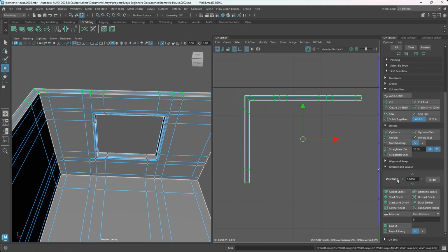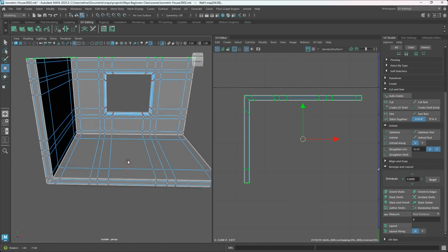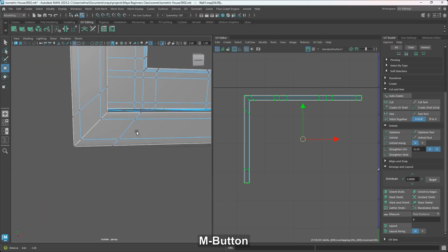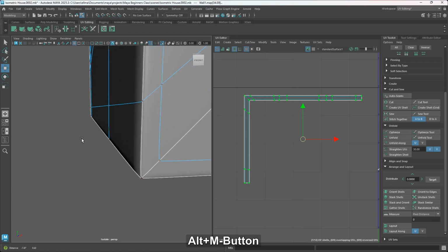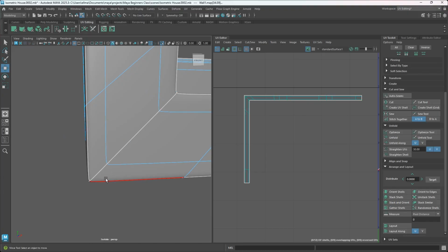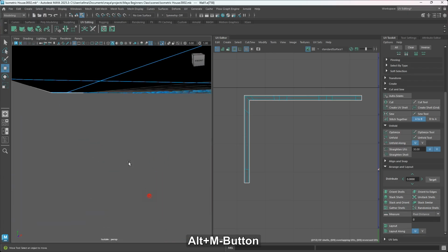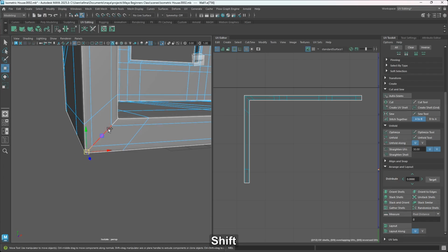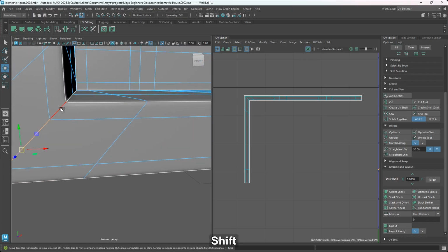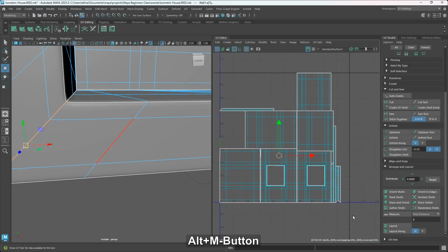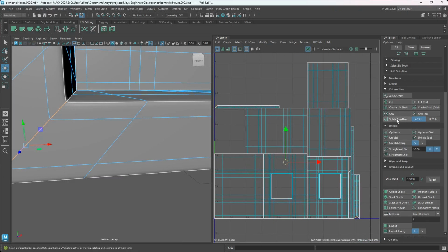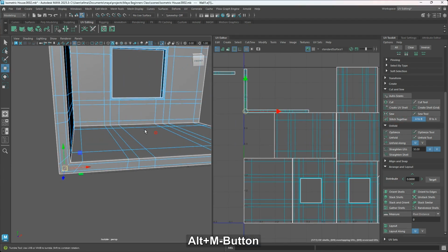After hitting on unfold, then you just orient the shell and lay it out. But the moment you hit on unfold, it is going to fix whatever error you have on your UV after you stitch together. So I'm just going to find all this part here and then stitch them together. So I can just go into the edge mode, look for these edges and just select. I don't want to select the loop round, so not that. So I'm going to select this edge, select this, and select this in my UV toolkit here. So I have both of them selected. I can just go to stitch together, and that is it.